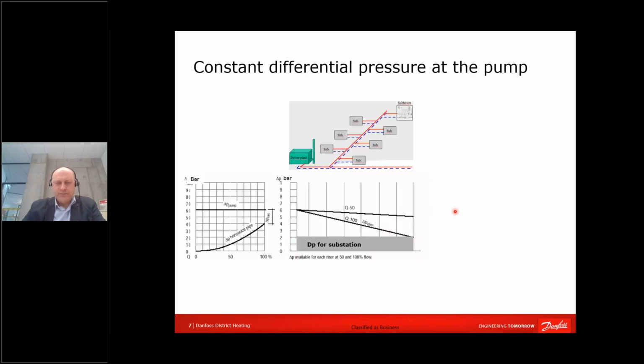So why is all that happening? Let's presume that the district heating utility is supplying energy with a pump which is keeping constant differential pressure inside the district heating utility. Then when we have 100% flow, we have pressure loss in the pipes, and only this very part is used for sizing of differential pressure controllers. Therefore, designers should receive data from the district heating utility about minimum differential pressure conditions in the station. Later on, the designer will have to chop the differential pressure to different components.